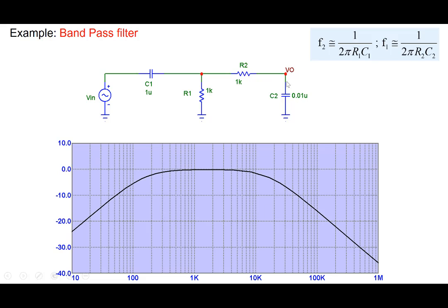And note that we wanted the low pass frequency to be higher here. So for the R2, C2 time constant, C2 has been chosen to be 100 times smaller than C1. That would ensure that the time constants are 100 times lower and frequencies are 100 times higher. So we combine them together and we can see a band pass kind of behavior here, right?